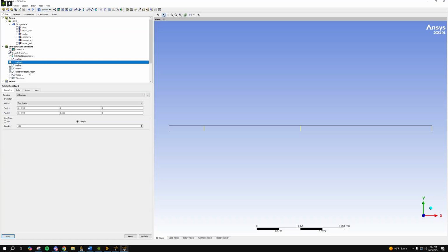And then we're actually going to also make an underdeveloped region. And for this, I did the same thing, location line, created my underdeveloped region at the 0.02. So this is going to be 20 millimeters into my surface and a height of 0.003 meters, so 3 millimeters, and make sure we have 100 samples on there. Just going to go ahead and click apply.